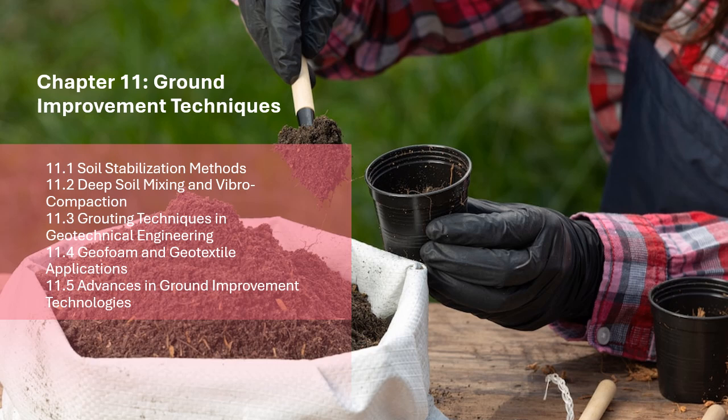Vibrocompaction increases soil density and improves load bearing capacity. Environmental impact. DSM can be environmentally friendly if non-toxic binders are used. Vibrocompaction has minimal environmental disruption and is non-invasive. Depth of treatment. DSM can treat deep soil layers up to 30 meters or more, typically up to 20 meters.